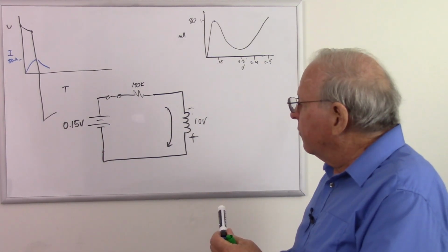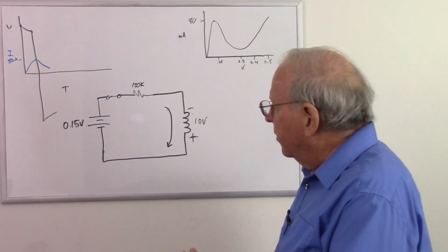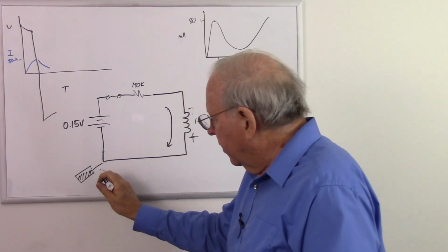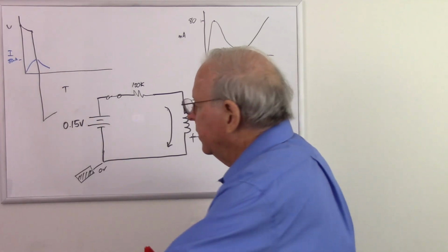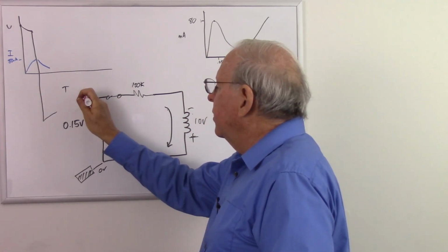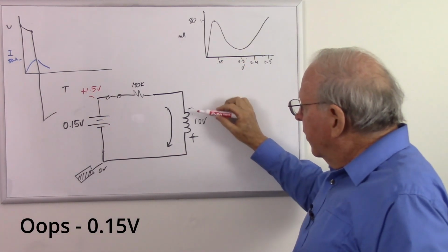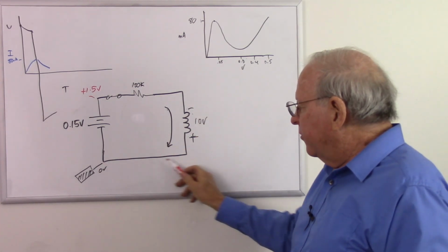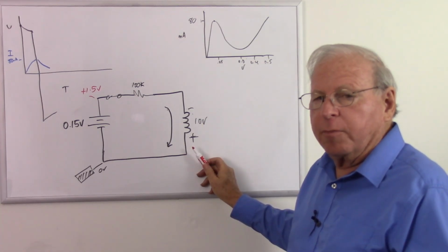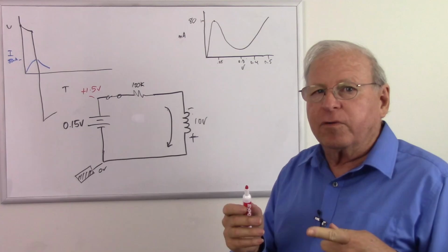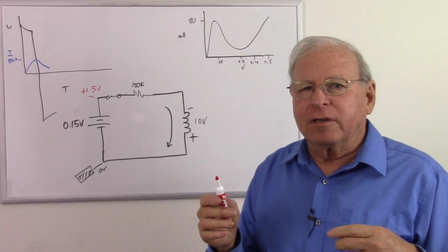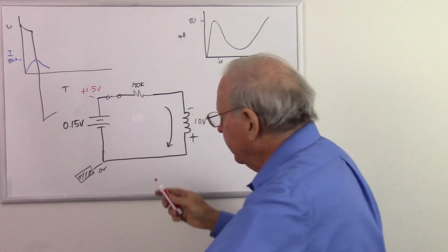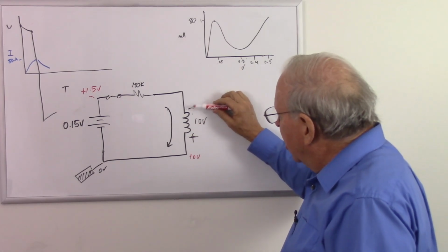So now we put on our Kirchhoff's voltage law hats and start looking at what the voltages are going to do around this circuit. So here is the black probe of our voltmeter. So that's going to be our 0 volts. We are going to have plus 1.5 volts here. And what are we going to have right here? Well, we have 0 volts here, and we are going down in voltage now. Remember, this has to be 0 volts. Why? Because 0 volts is where you put the black probe of your voltmeter. That's by definition, that's where 0 is. Remember, 0 volts is not the absence of voltage, but just some voltage that we have designated as the point where we measure our voltage from with my imaginary black probe here. So the voltage here is going to be 10 volts lower.